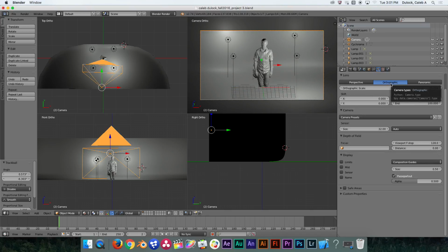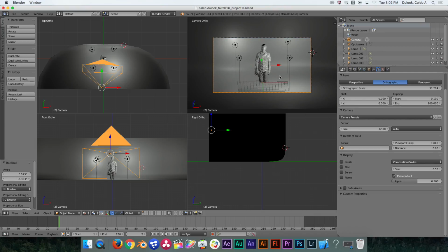But that's how we can switch our camera from being perspective distorted to orthographic non-distortion, which is what I'll recommend you use. We're not going to really play with any of the other camera settings at this time. I will talk in the next exercise about how to change the shape of your camera's viewing area and the quality of it so that you get nice still image renders out of Blender. But that's the basics of how you can manipulate your camera in the scene. And again, what it sees through the lens of the camera is what you can render out of Blender.